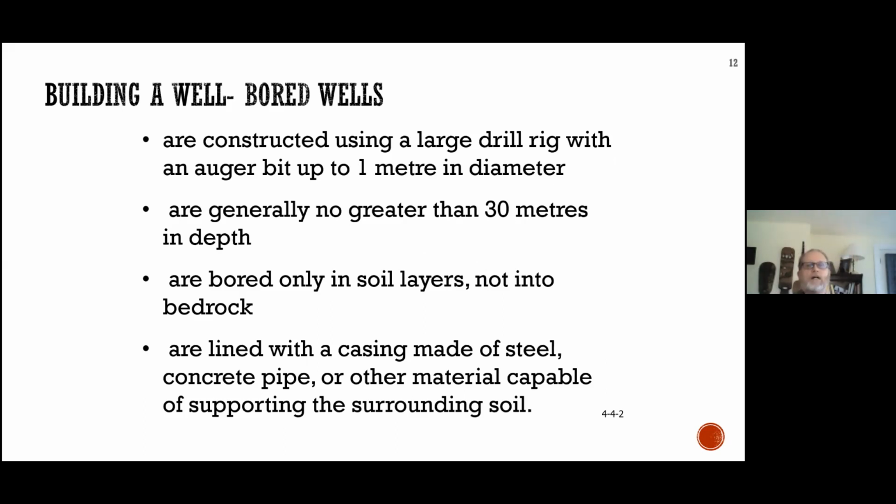using a larger drill rig. The bit can actually be up to 1 meter in diameter, so much larger casing, but typically not going into bedrock. Bored wells, the key characteristics, up to approximately 30 meters in depth. And they, again, are very useful and versatile where water table is high. But they're typically not designed to penetrate bedrock.